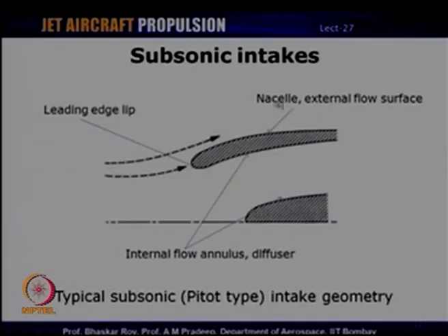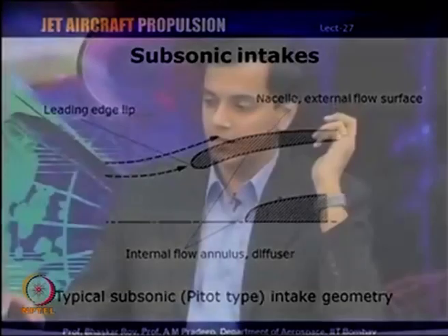One is of course the external flow, which I mentioned that we should try to minimize the drag associated with, and under certain operating conditions there could also be flow separation external to the intake itself. Besides that, there could be flow related problems on the intake surface or on the hub surface. So, it could be either on this surface or on this surface or external to the intake, and all these three are basically a result of the intake operation under various operating conditions.